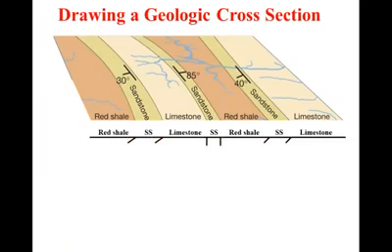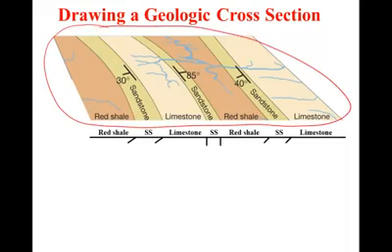Okay, so all I've done so far is transfer all the information shown on the map onto my cross-section line. In other words, all I've done is reproduce what information is on the map and show it on my cross-section. There hasn't really been any thought or interpretation involved yet. I'm just reproducing what the map tells me is seen in this area: names of the rocks, locations of contacts, and dip directions and angles drawn in using a protractor.